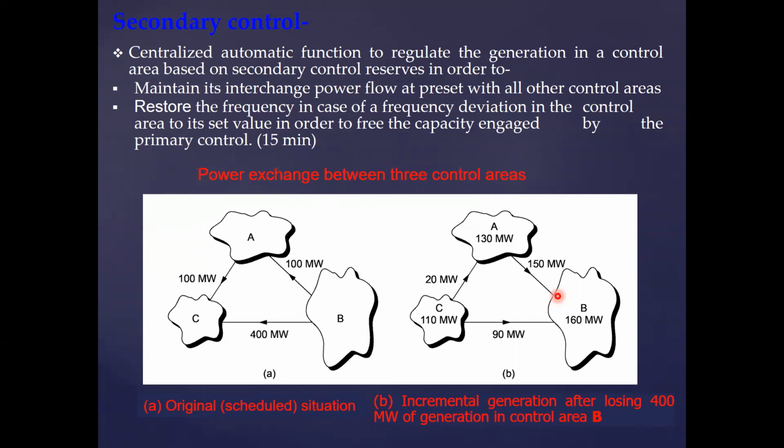And frequency deviation is again affected by the contingency level, how much the load has changed, or, as in this case, how much the generation outage has changed. Any mismatch between the generation and demand will translate into frequency deviation. So the supplementary control will try to modify the change in the generation from the generators here, right?